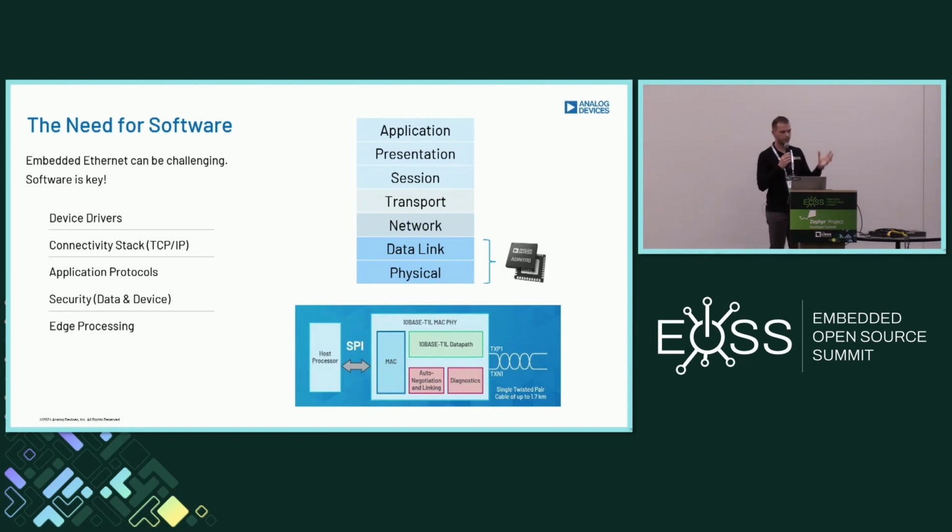Outside of this, key software components include things like device drivers for communicating between the host processor and the PHY or MAC PHY. The connectivity stack is again a key requirement from a software standpoint. The TCP/IP suite is pretty much the de facto standard when it comes to implementing networking connectivity these days, and it's vitally important that embedded devices have a full TCP/IP stack to ensure that they are interoperable with existing IP networks.